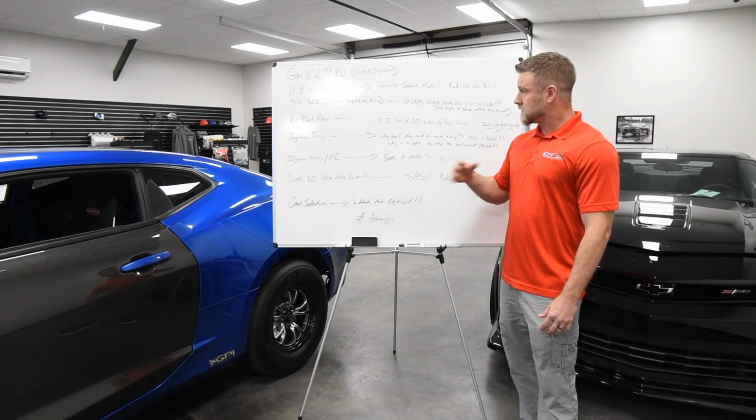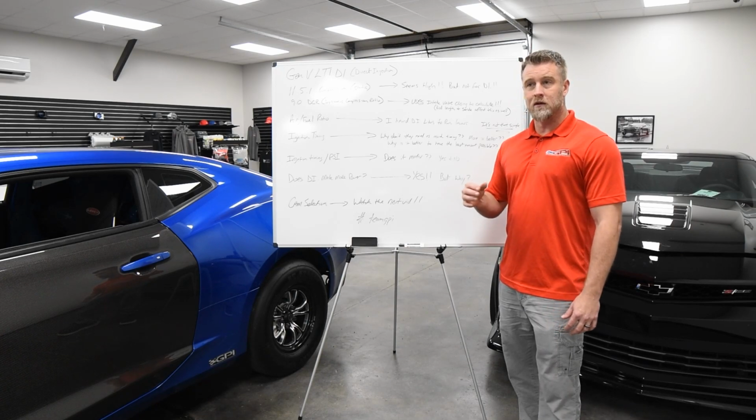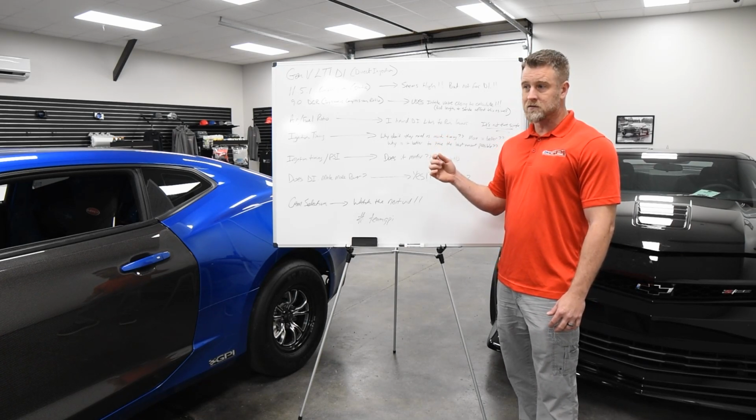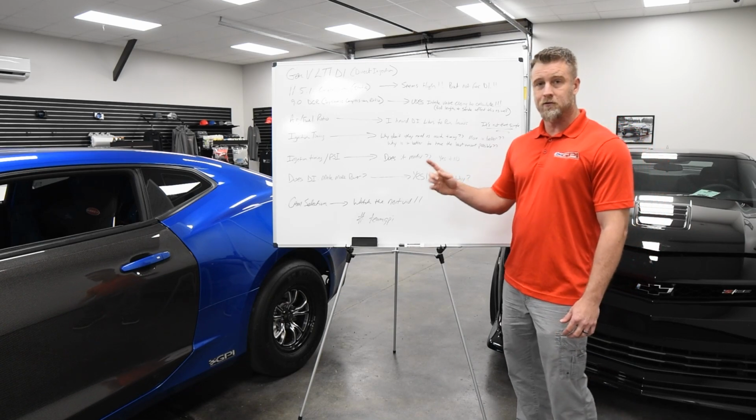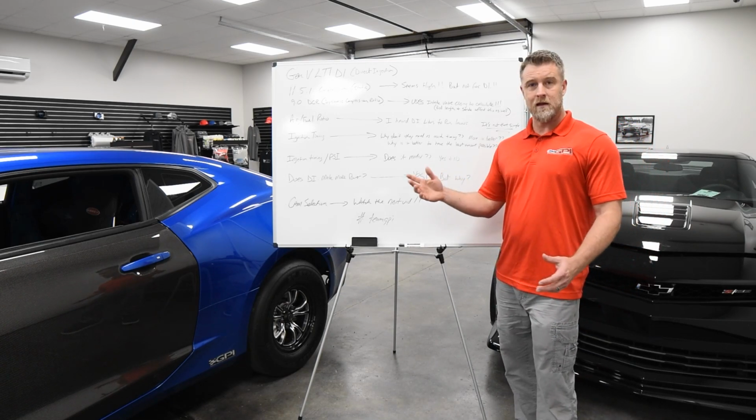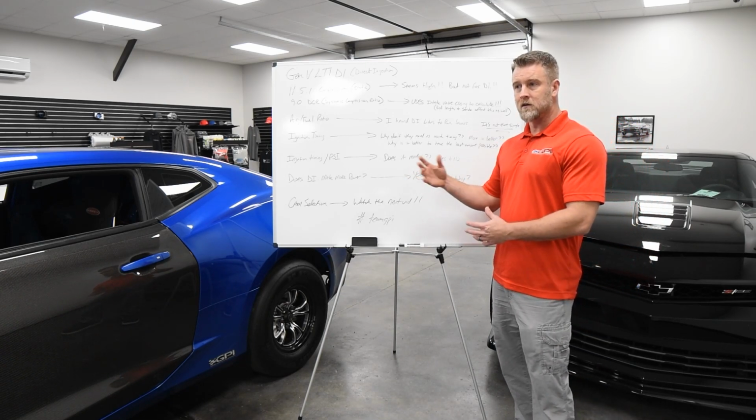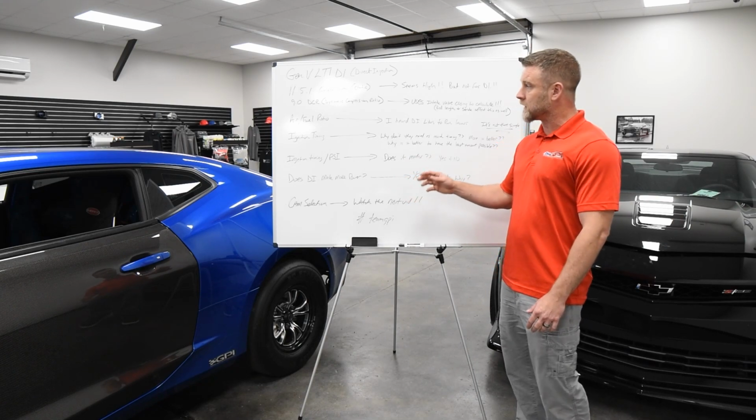So I would say, if it was my advice, I wouldn't err to the lean side of things. Run the fattest air-fuel ratio possible to make good power. Start from there. Go to the track and see what it likes from there.